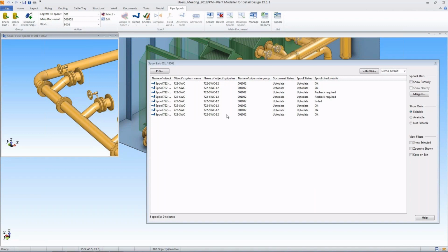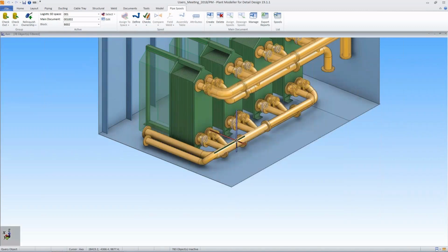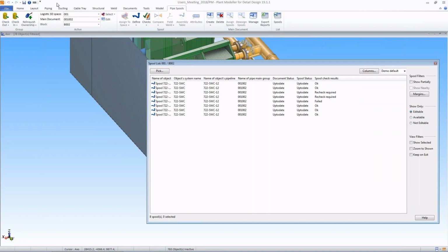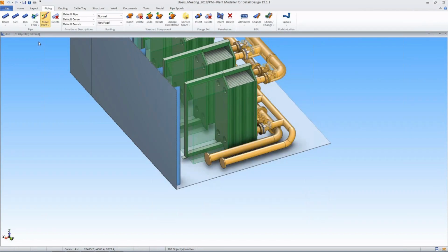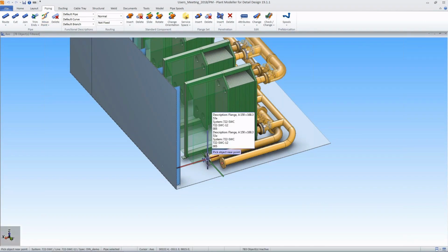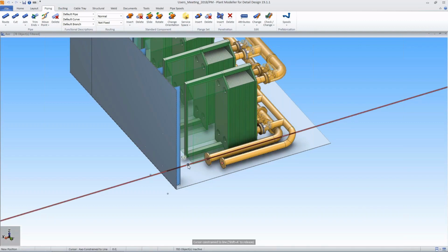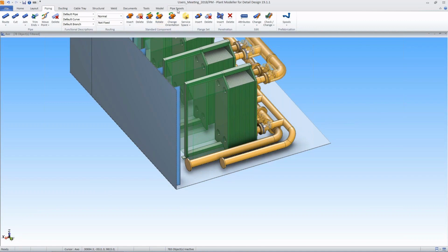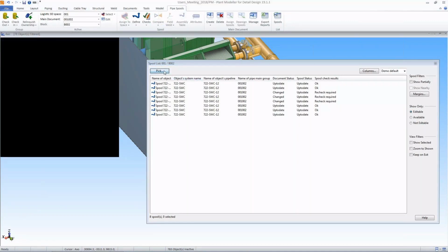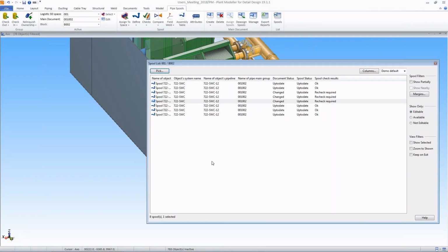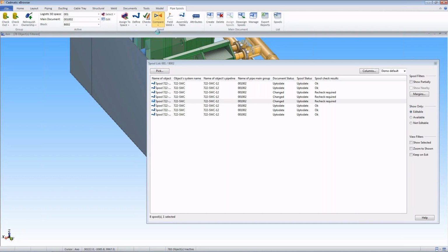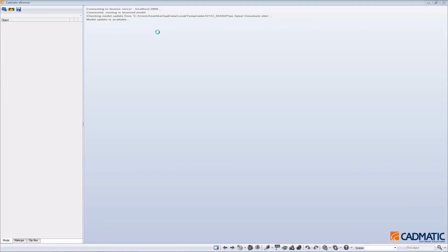That means that now if I go to do a slight modification to this spool, here I'll go and maybe move the point slightly according to X. Now I'll go and compare the model object to the one represented in the spool drawing. The comparison opens in eBrowser.